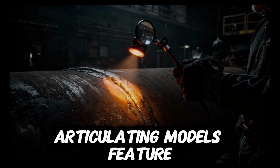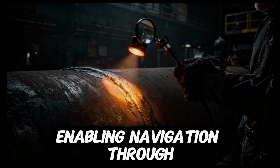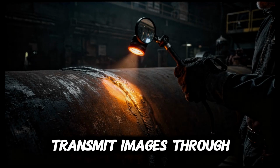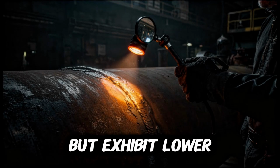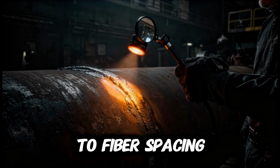Articulating models feature distal tip deflection up to 120 degrees, enabling navigation through complex internal passages. Fiber optic scopes transmit images through coherent glass fiber bundles. They offer flexibility and durability, but exhibit lower resolution and a characteristic pixelated texture due to fiber spacing.